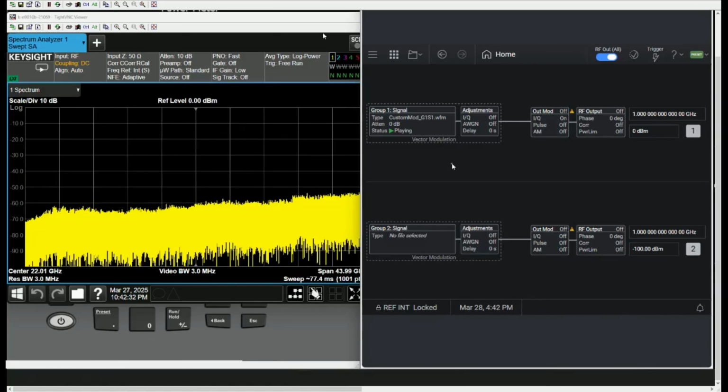I'm going to walk through with you quickly how to set up the 16 QAM 40 meg bandwidth signal. Before that, we just want to calibrate, just to make sure the offset has been accounted for. This is what I will do normally. I'll set the frequency and the power output from the signal generator. So let's turn that on.